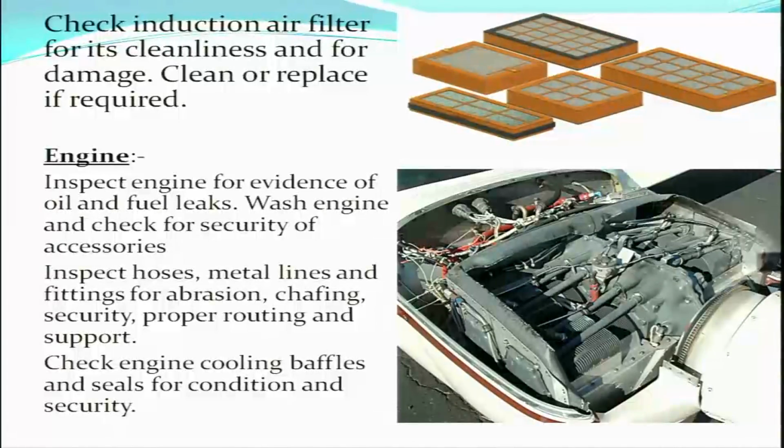Check engine cooling baffles and seals for condition and security. These are your cooling baffles, these are the engine baffles. These baffles need to be inspected for seals, for condition and security.